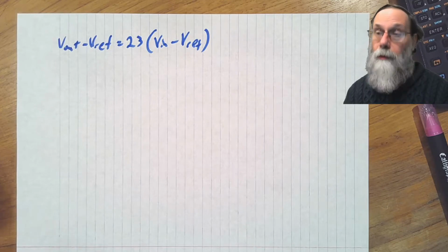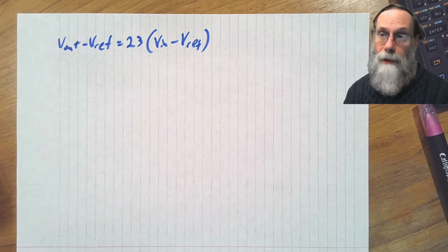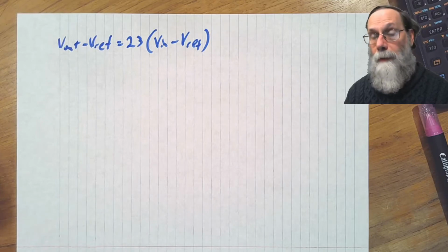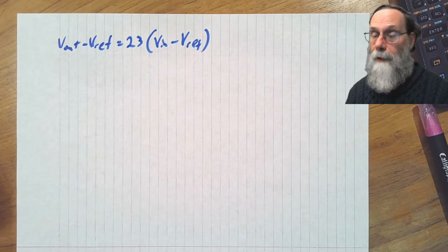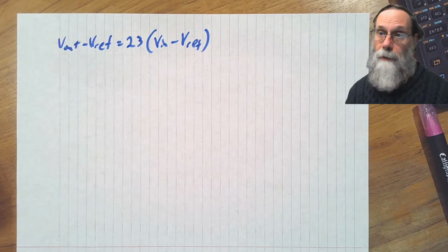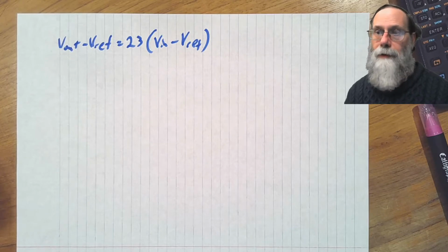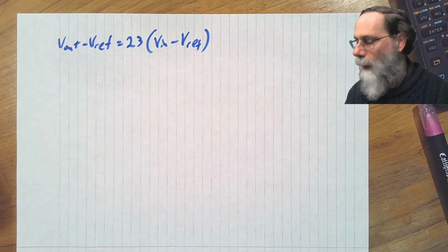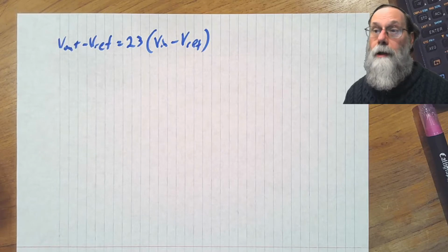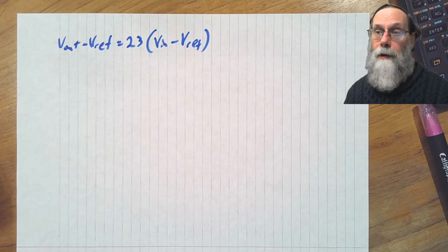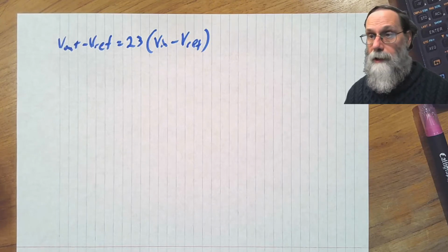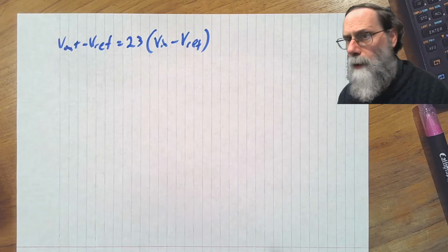In the real world, we would, after doing this design, take a look to see what the effect of input offset and gain bandwidth product and any other limitations that the amplifier has on the design, to see if we have to redesign something in order to take account of these imperfections. But we usually start by designing as if our amplifiers were perfect op amps, and quite often that's good enough and we do not have to make any corrections to that design. Alright, so how do we go about doing this?